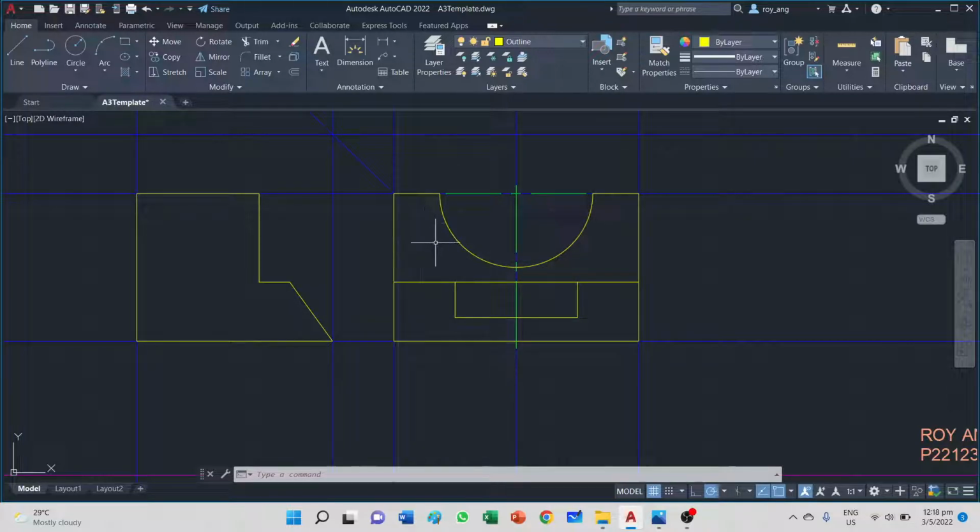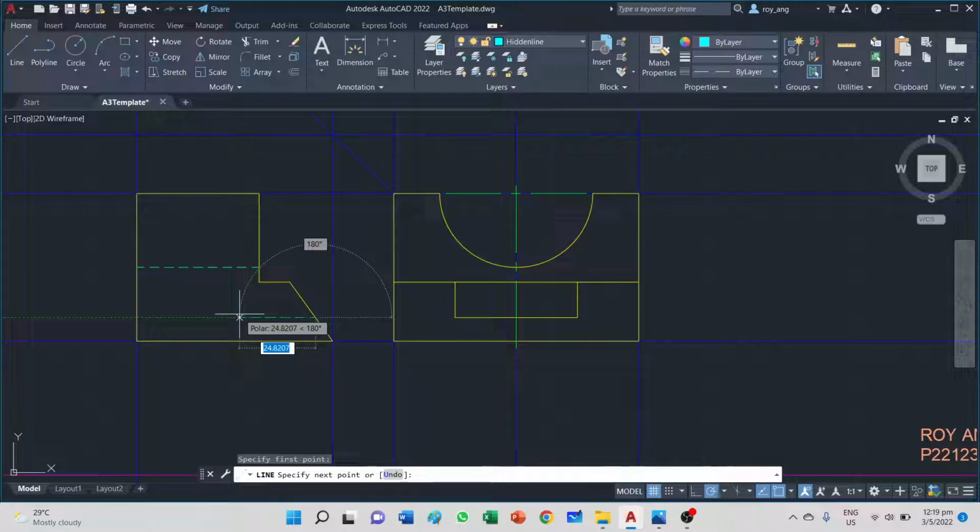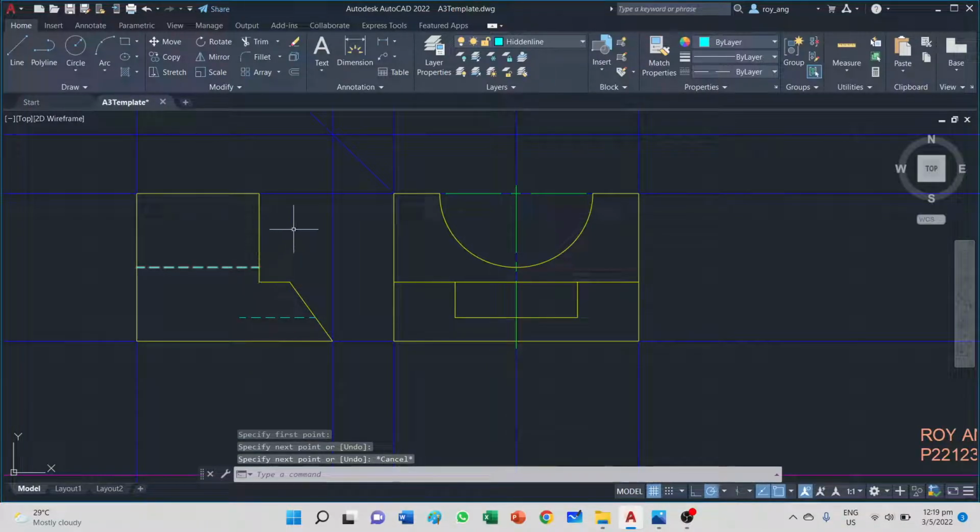There are some hidden lines here. I'm not going to draw that. Then I'm going to go back to my end view and I can draw my hidden lines for my end view now. One of the first few hidden lines that I can draw is this hidden line that is here, and it goes right across here. Then the next hidden line that I can draw is the cutout that's here, and it goes somewhere here, and I'm not sure how much it goes to because it doesn't give the width.